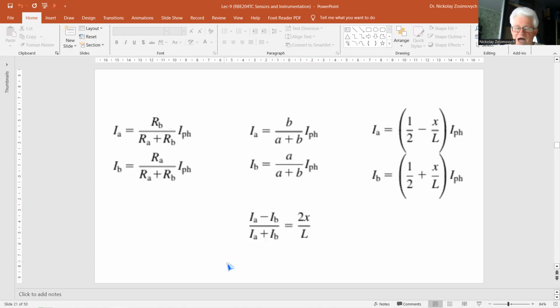A more in-depth analysis of the effect of environmental illumination sources for a two-dimensional PSD. In general, there is just one light spot from the laser, of which the position can be detected. In case of multiple light spots, the beams can be distinguished using modulated light at different frequencies. The PSD can be used for contact-free displacement measurement.